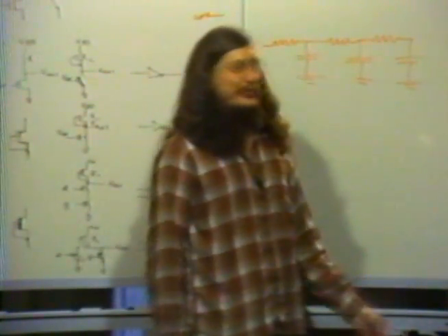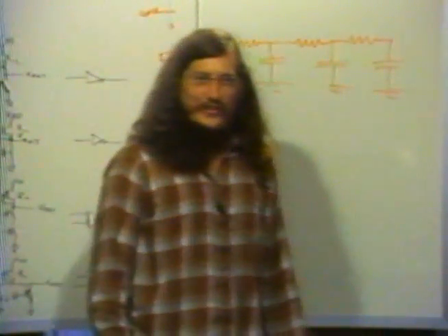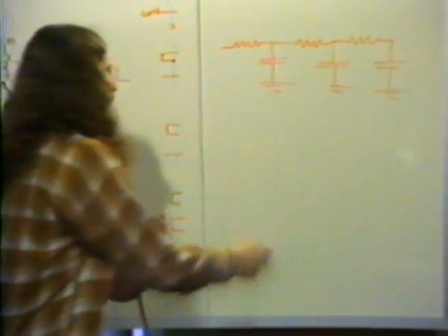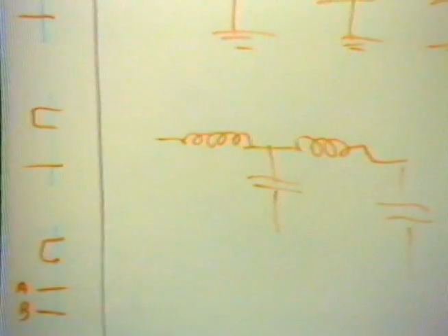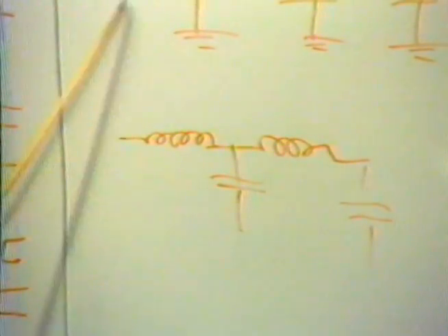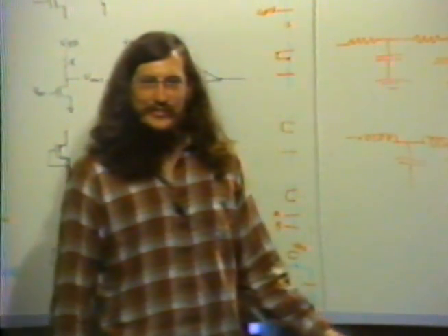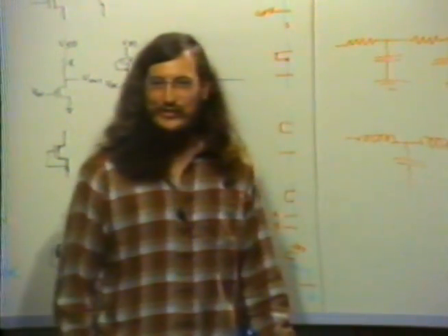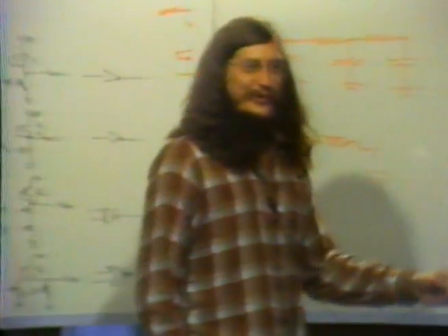One other kind of delay in wires, which I didn't mention on the chart, but which you might think of, is speed of light delay. That is, a metal line is really a transmission line. It has negligible resistance, but it has some slight inductance, as all conductors do. This thing propagates a signal much more quickly than the resistor capacitor transmission line. And in fact, you get some reasonable fraction of the speed of light. The reason I didn't mention that is because chips are fairly small, and in current technologies, the speed of light is not a limitation. I haven't really figured out when it will be, but I wouldn't be surprised if it starts coming in.